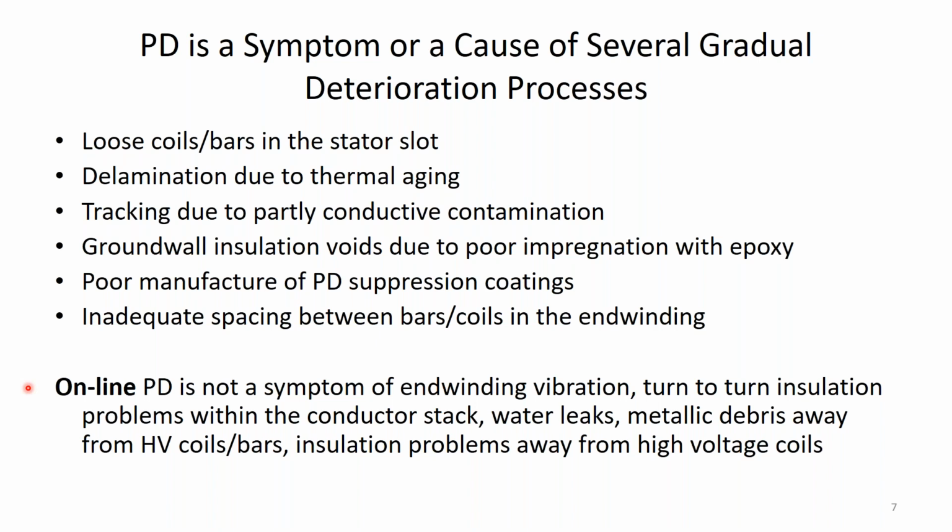And it turns out, although these might represent the most common of the 25 or so failure processes that can occur in stator windings, if you read my book, and these are by far the most common ones, some of them are caused by manufacturing, some caused by aging in service.